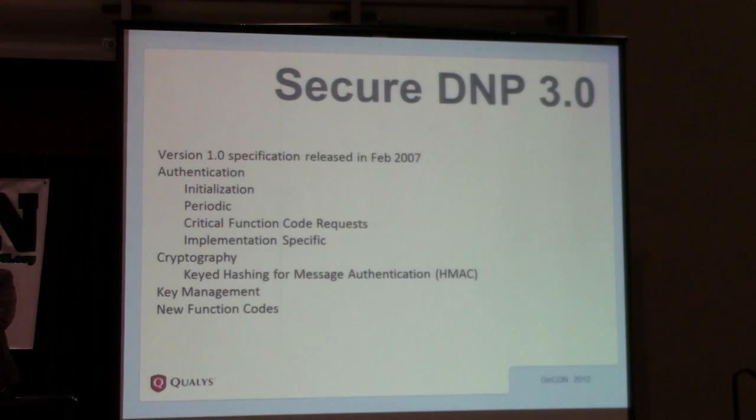But all is not lost. In 2007, the DNP3 organization came up with a secure version of DNP3, which has cryptography, hashing, key management, and all the sort of functions that you expect from a modern protocol. So if you have DNP3 in your organization, make sure that it's running the secure version, which is the post-2007 version.